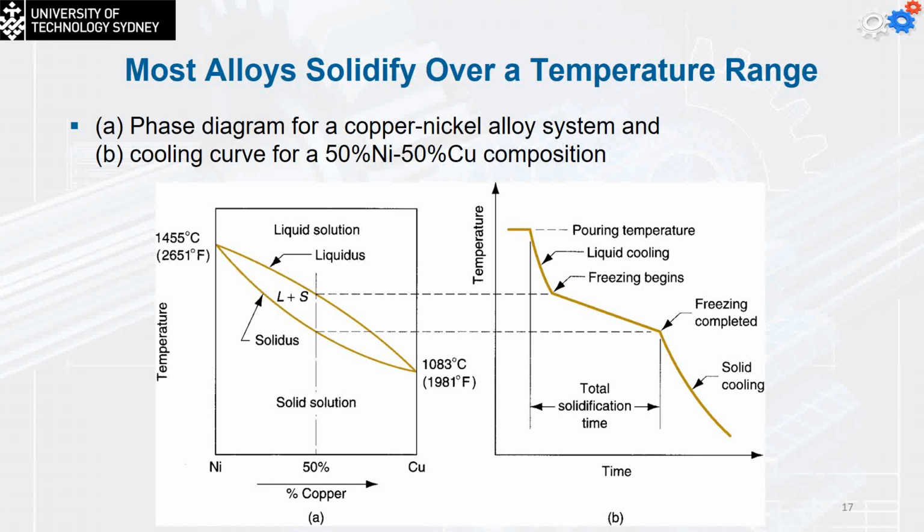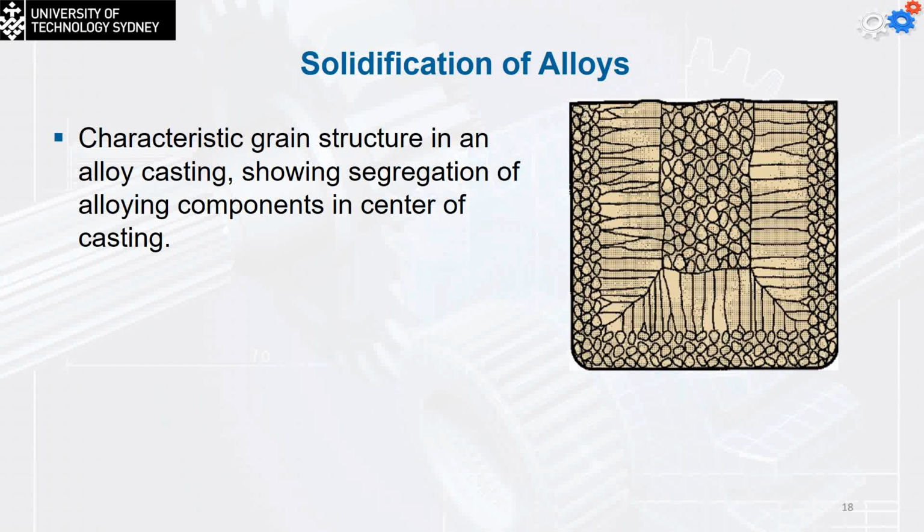So what happens is as follows. Once again, the outside is going to be chilled very fast and start to cool down. The mixture in between is going to be a longitudinal one, where the metal with the higher melting temperature starts to solidify first. Then the metal with the lower melting temperature is solidified second, and it solidifies more rapidly because this one lost most of the temperature.